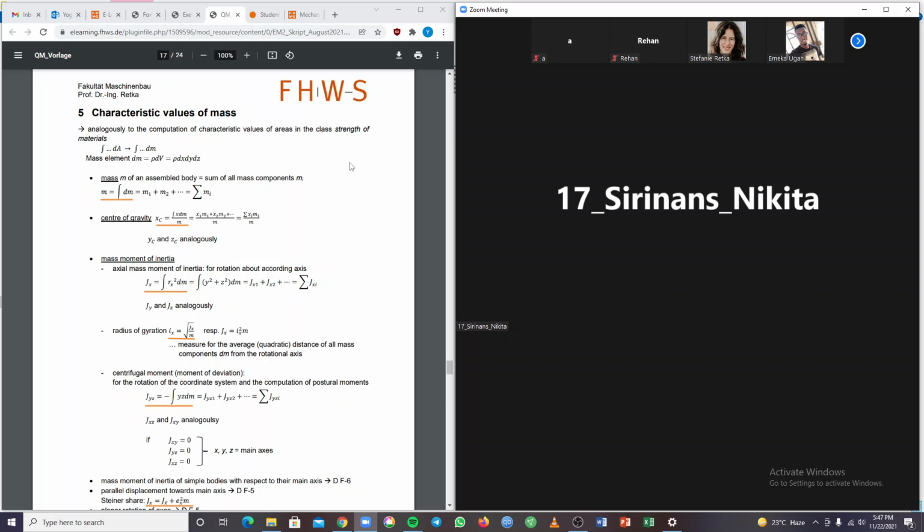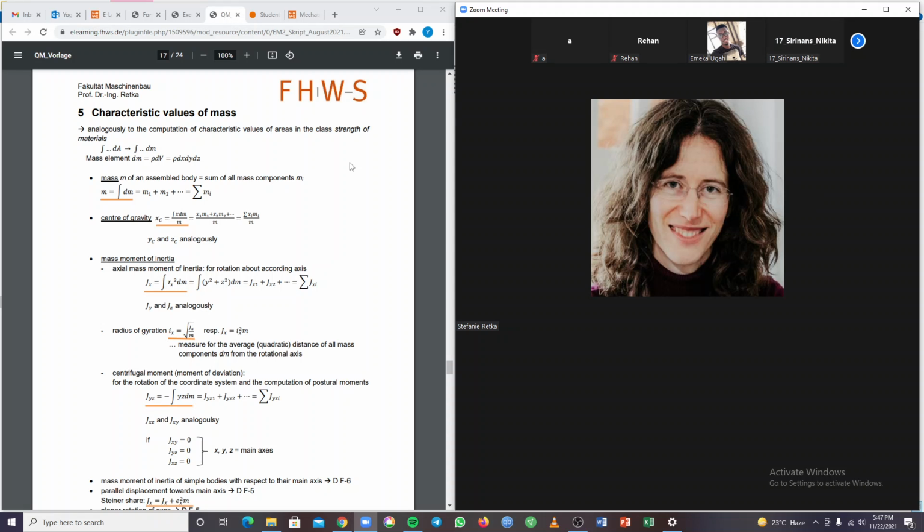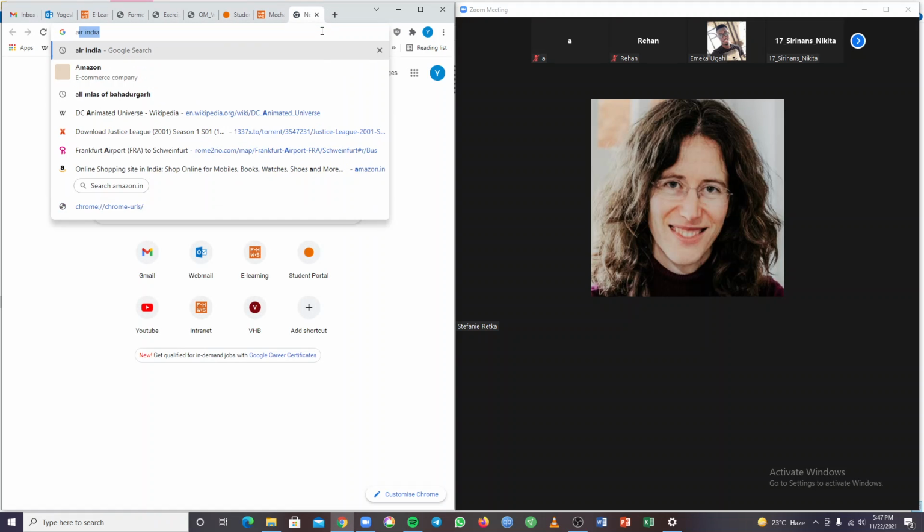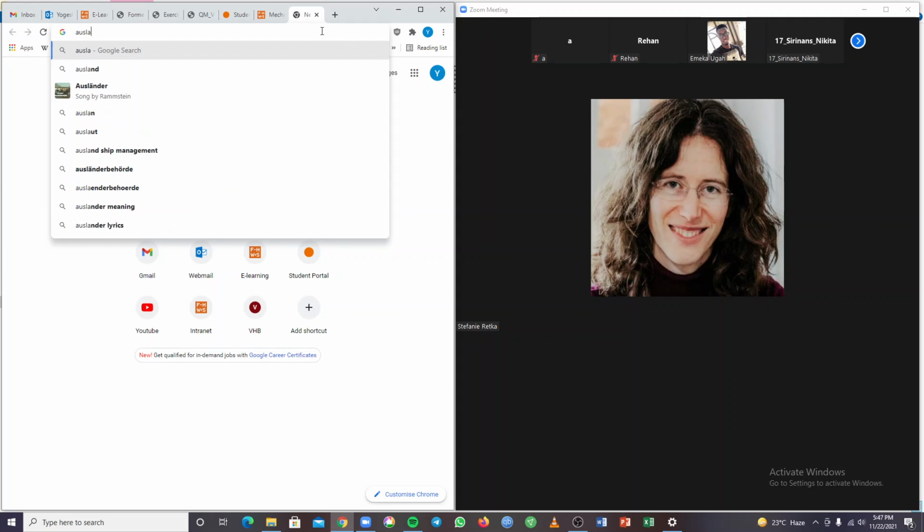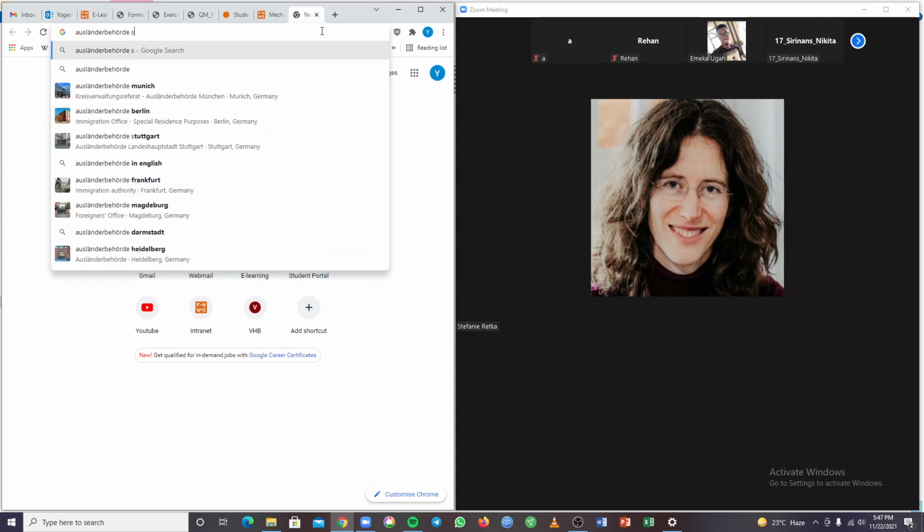Okay. First of all, you have to decide how many kinematic variables are there in your system. How many types of motion, okay? So, for example, a translation and a rotation, or 2 translations and a rotation. Simply draw them in your free body diagram, like we did for the cylinders and masses connected by ropes, and then count them. It's important that you only count either distances or velocities or accelerations. Don't double count them, okay?